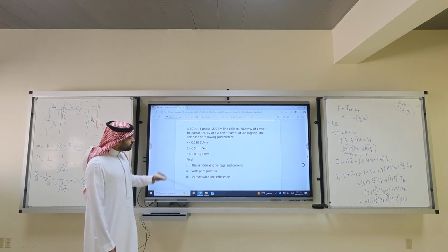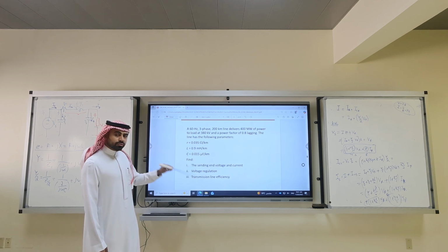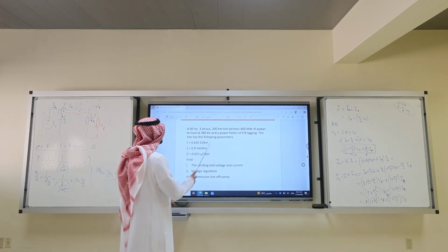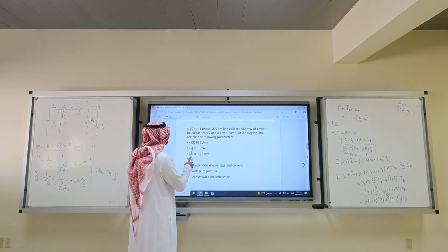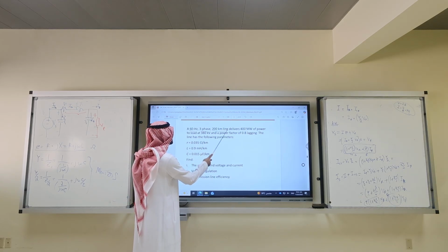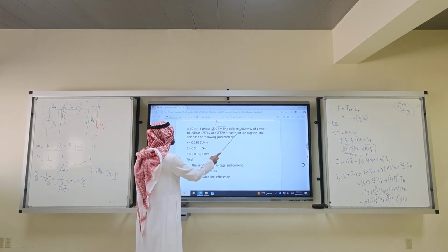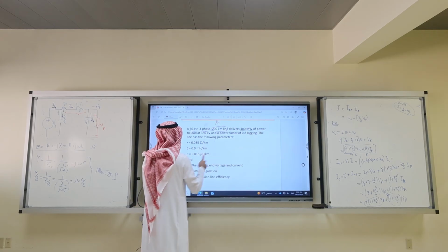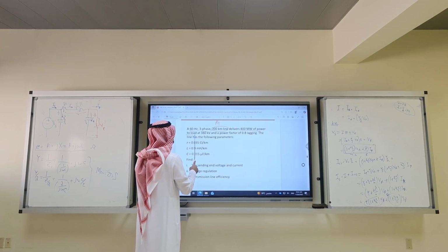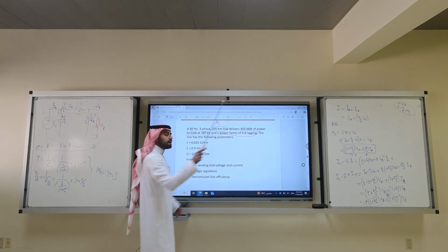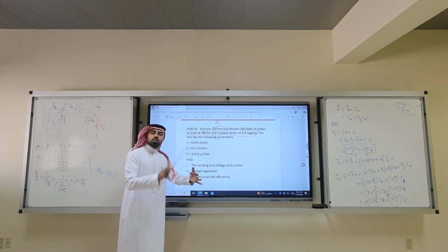So I'm not gonna solve it, but I will show you today. What time is it? We have 9 minutes. So 60 hertz, 3-phase, 200 kilometer. This is a medium line, right? Yes. It delivers 400 megawatt of power to a load of 380 kV, at a power factor of 0.8 lagging. This statement describes the VR, IR, PR.